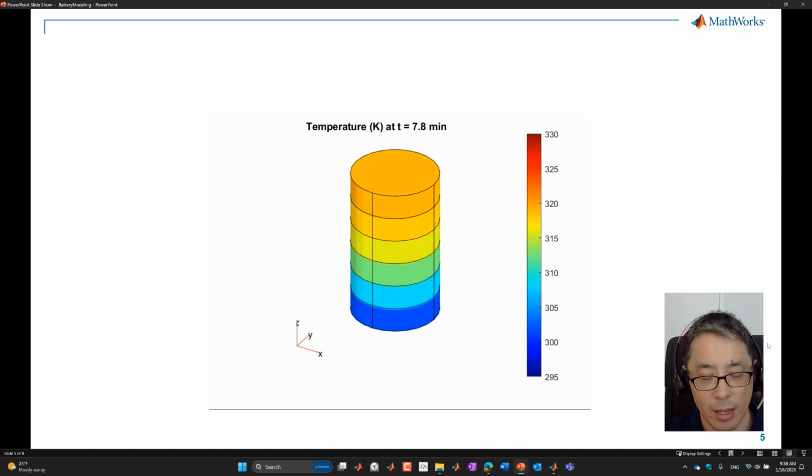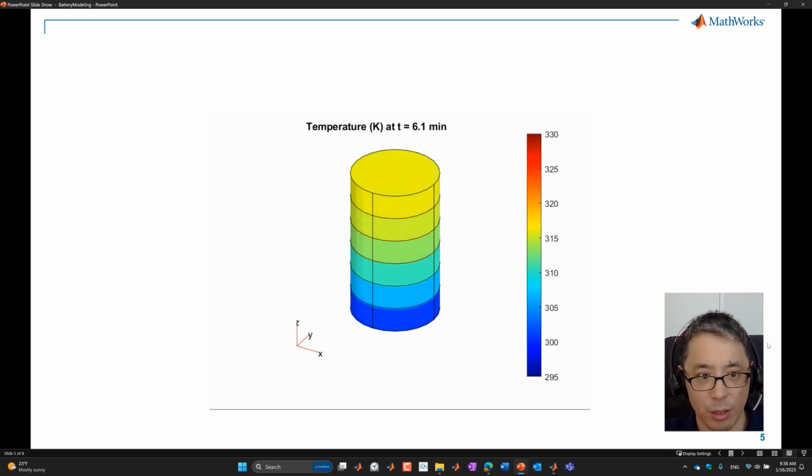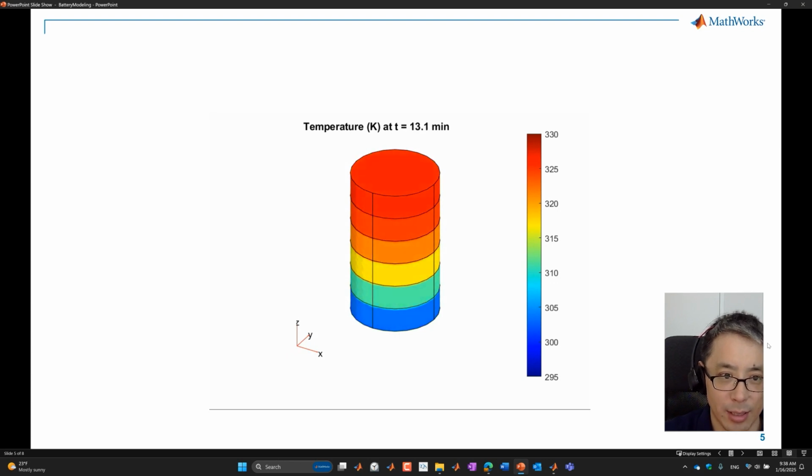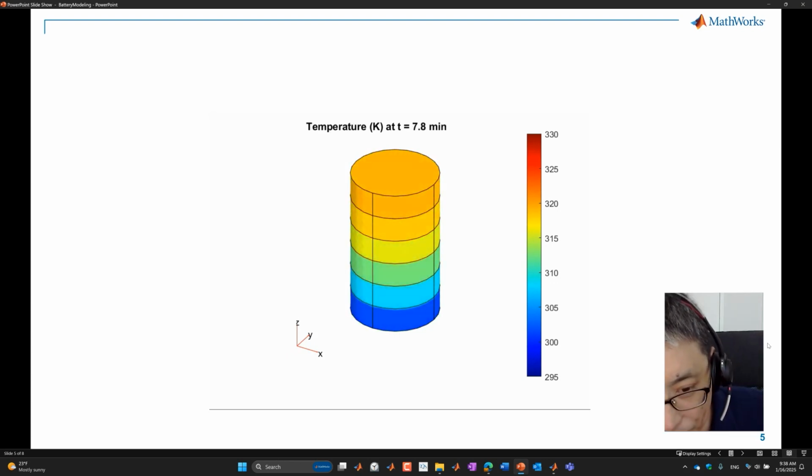And it's a small animation we can create using the tools provided by MathWorks. In particular, we are using a PDE Toolbox visualization function. Then we are writing frames of plots to a video, and then saving the video file. So that's what's going on in the script I just showed you a moment ago.